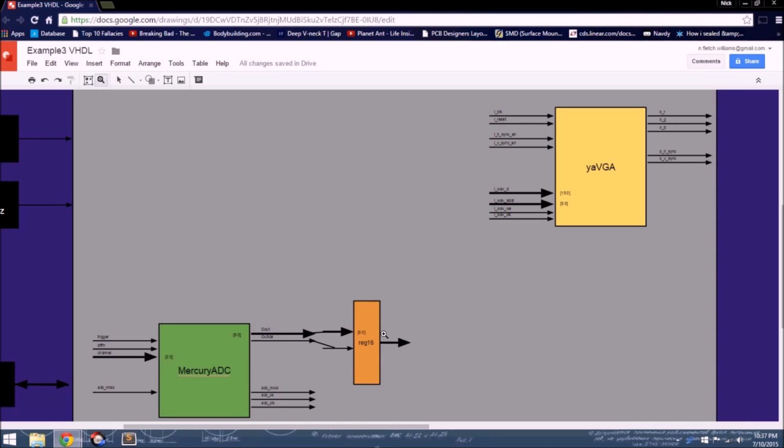Now before I introduce the rest of the components, let's think about what we want to accomplish for a second. We want to build an oscilloscope that auto-triggers on the falling edge of the first start bit of a 9600 baud UART signal. Then we want to display the entire waveform in a good proportion to the rest of the screen on a VGA computer monitor. Then when the waveform is captured, stop creating the waveform. So the logic is actually pretty simple.